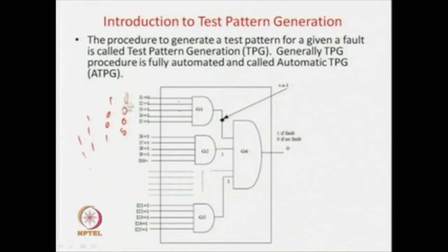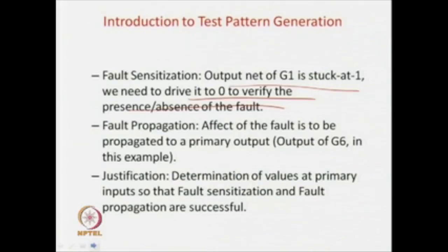So, sensitizing means if it is a stuck at 1, you have to apply the reverse value. So, I have to apply a 1 over here. That is actually called the sensitization. Now, the next step is called the fault propagation.